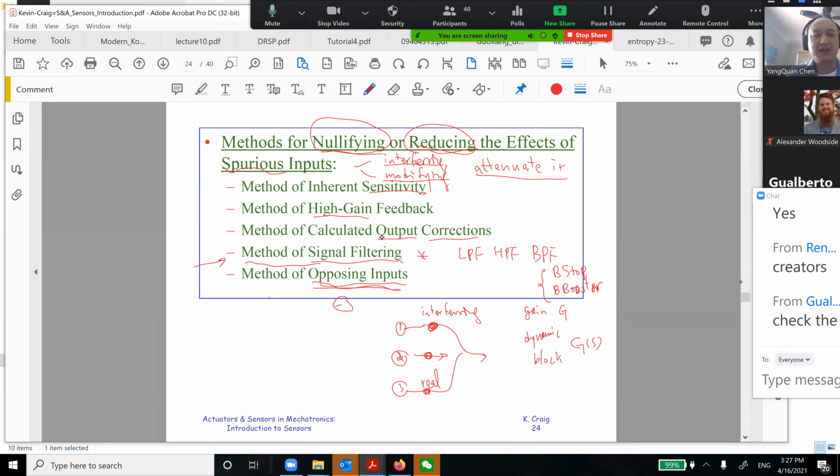How about we just get the output, then make corrections to it? If you know the table is tilted, instead of solving the table leveling problem, which may be very expensive, you just live with it. After I got the readings, I do some corrections, given the information I know about the tilt level.